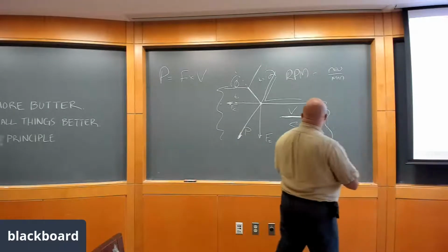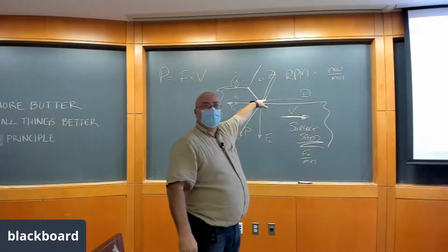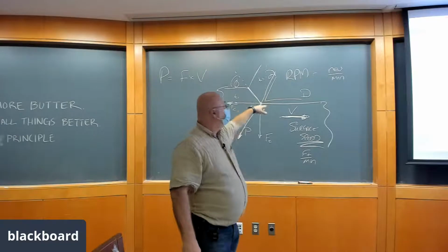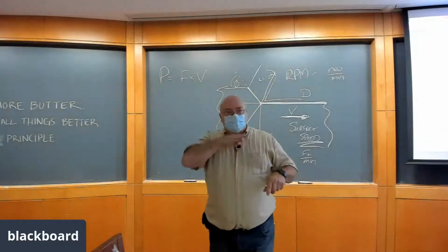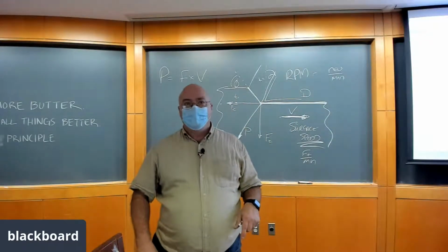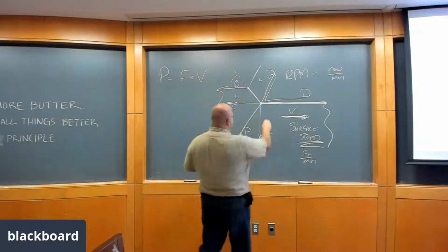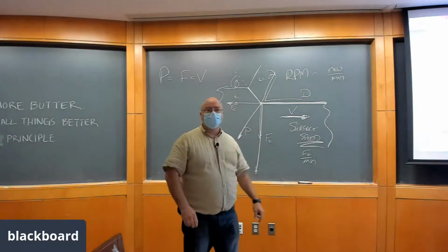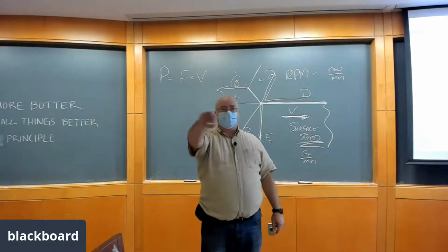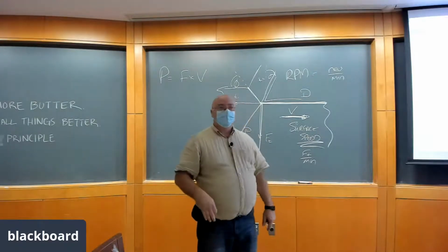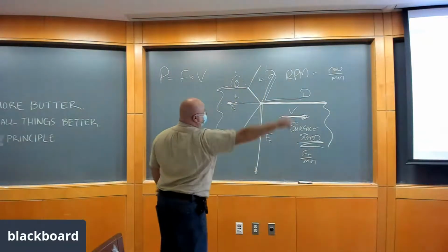Diameter will help us get there. So where's the diameter in this diagram? See this straight line here? This planar surface that's level in a straight line? That's just zoomed in on the outside of the part, right? So the diameter is down that direction somewhere. We're just zoomed in so much on that part of the part that it looks like a straight line. It's like the earth in front of you looks like a straight line, even though there's a horizon, right? So the diameter is in the rotation of the workpiece going past the cutting tool.